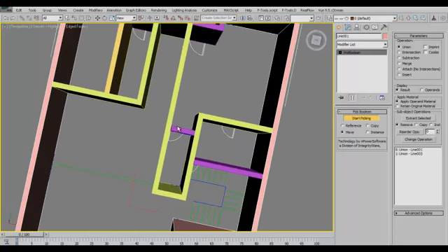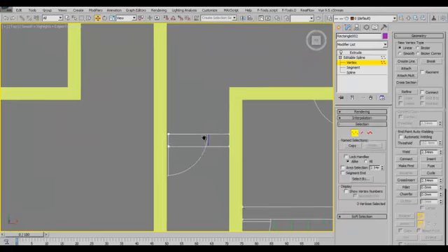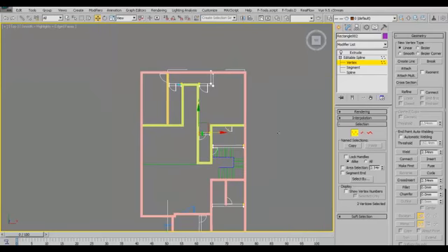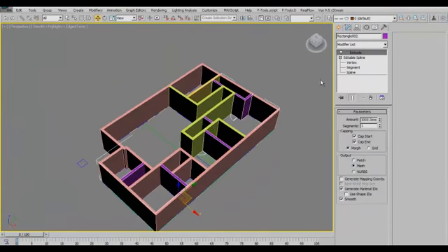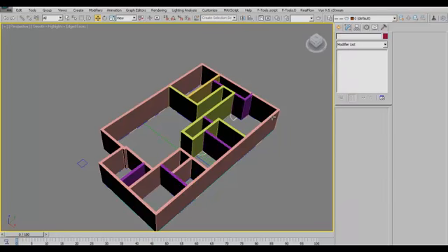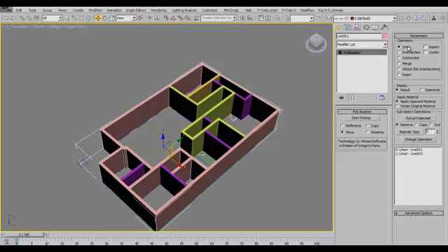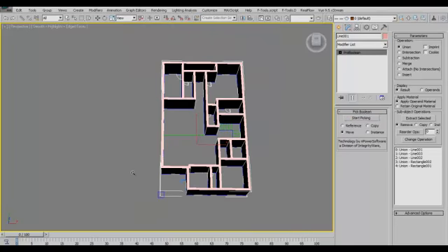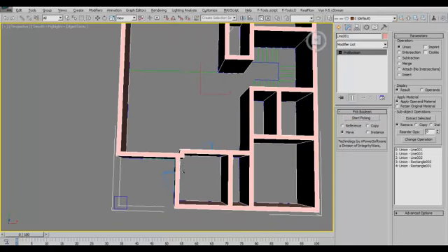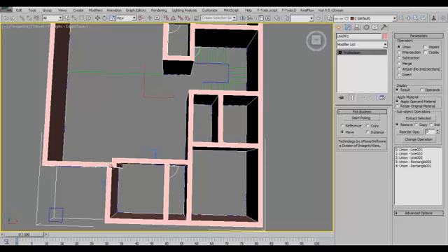I'm undoing that. I'm going to make sure it goes back to that point, and we go there. Then we use our Boolean and continue with the Boolean operation, because we still have that Boolean on this particular object; it's not on the other one, but it's always on the one you applied it to. We can always go and make sure the union is still on, and it merges them all. Now we have that wall as a complete single object, and at places where they meet, if they meet each other well, it doesn't form any seam at that point.